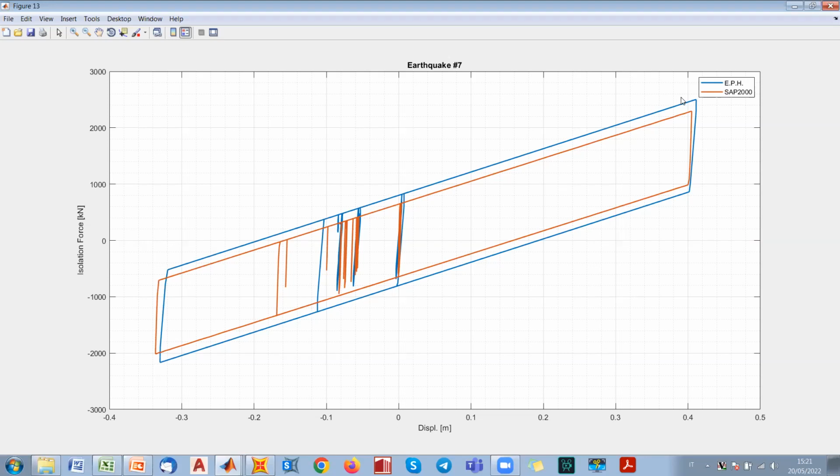Okay, because actually for lateral bearings we have just 4 bearings, 4 isolators at the corners, and the remaining supporting points are represented by flat sliders. So this means that we have the internal points of the structure, which are represented by flat sliders, and these are actually the points where we have the maximum value of vertical reaction, because we have the internal points, so we have the largest amount of external loads applied to all the floors. So maybe to consider the average vertical reaction is not the best solution for comparison.